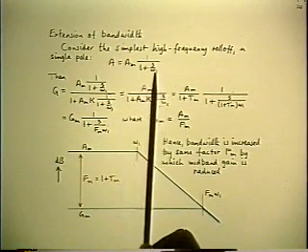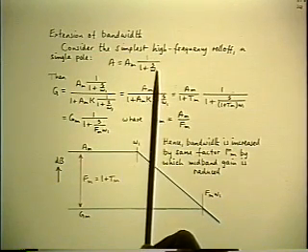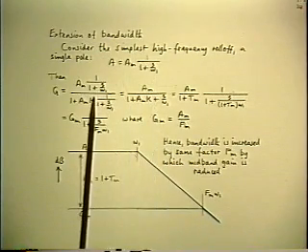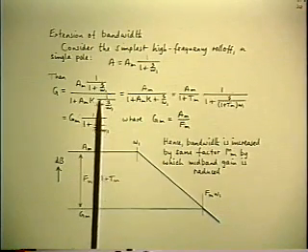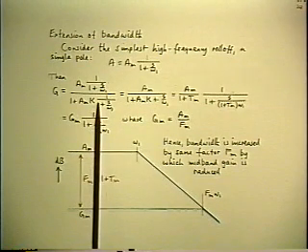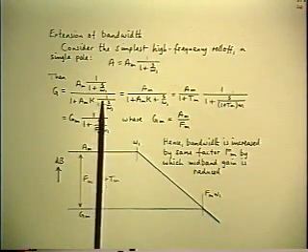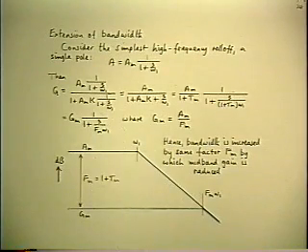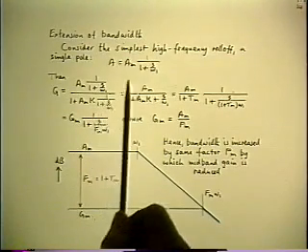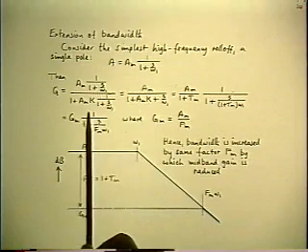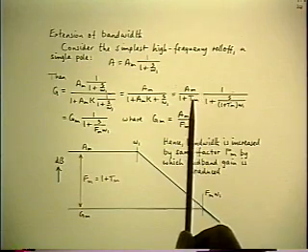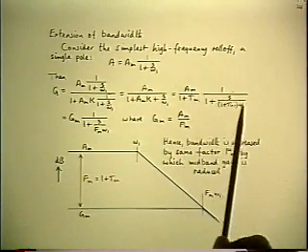A midband value AM and a pole at omega 1. What is the closed loop gain G? Well, it's a simple algebraic substitution into A over 1 plus AK. Let's assume for the moment that K is flat, doesn't have any corner frequencies. Of course, this isn't necessary, but let's keep it simple to begin with. So K is simply a constant. So the direct substitution of the A into the formula and rearrangement into the factored pole-zero form gives you this result, namely a flat gain and a single pole.